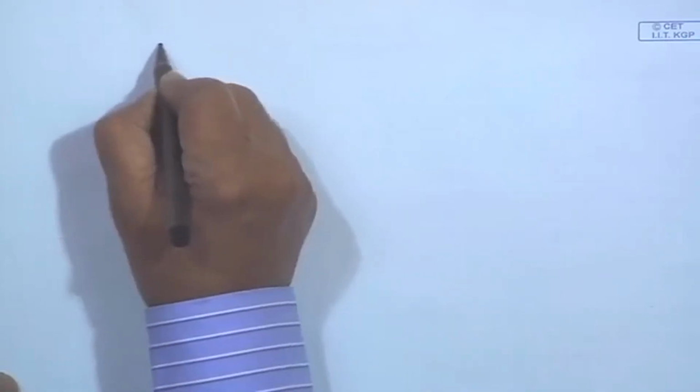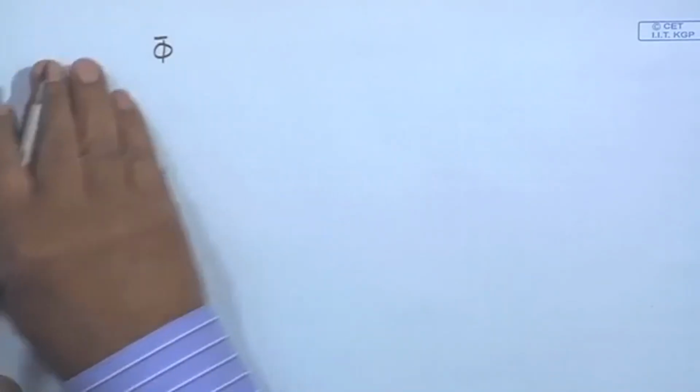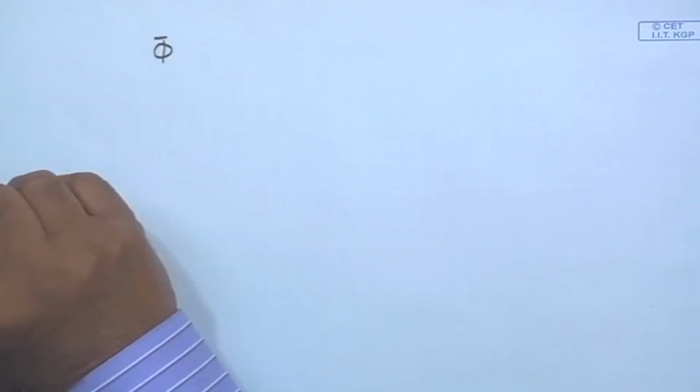Now, phi bar is a meteorologic statistic which combines with the operating condition. So, given a location and the solar radiation distribution from day to day, if the system is supplying energy at 60 degrees, 50 degrees, 70 degrees, the solar radiation available to you above the critical level will be different. So, phi bar will be different. This is a good indicator combining the meteorological statistic and the operating parameter, the main one being the critical radiation level or the temperature at which you desire the energy delivery.